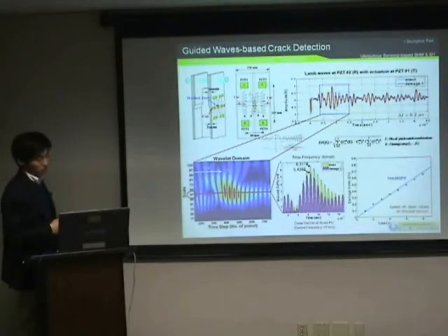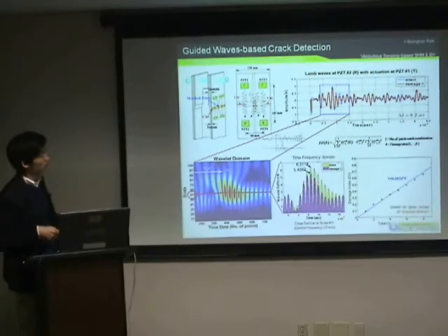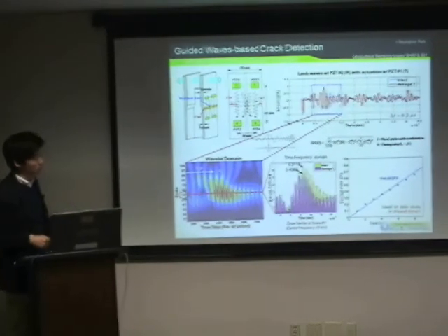This is for guided wave based damage detection using the same steel truss member. As you can see here, we can apply a wavelet transform to the time domain data. We can monitor crack growth by using the wavelet coefficient from the guided wave data in the time domain.